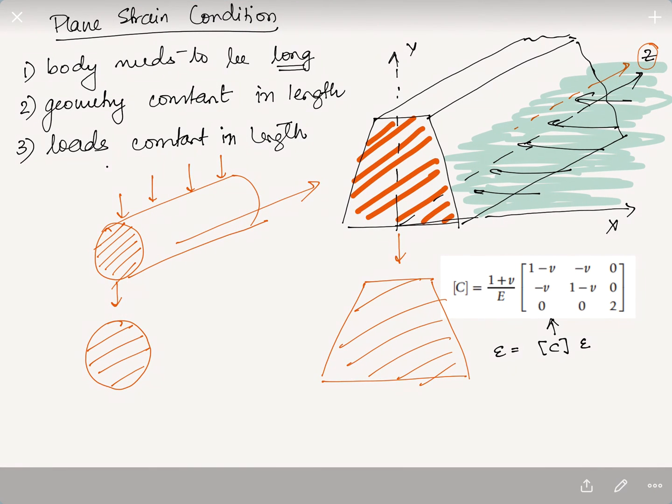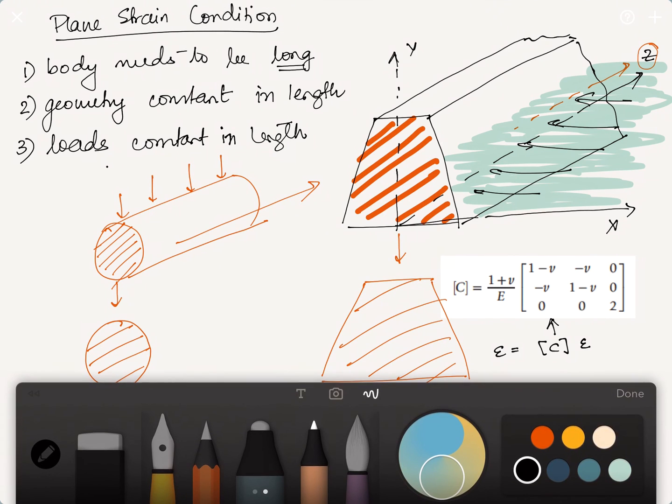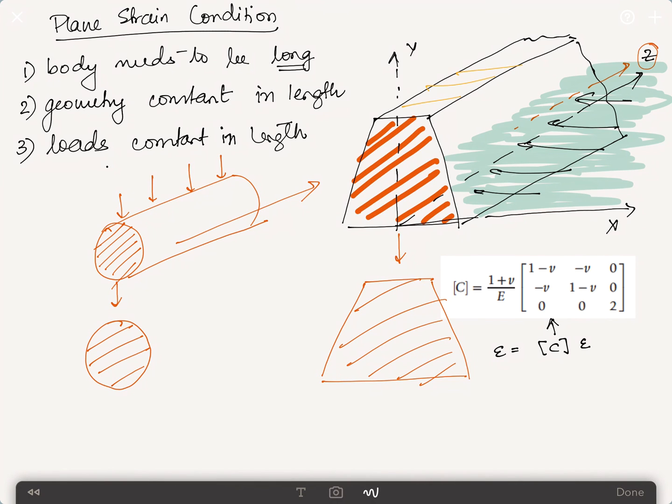The difficulty here is that you have to make sure that you've made the right assumptions and that you're able to reduce a certain part into these cross sections, which can be quite tricky. But in the end, consider the change in computational effort: instead of making this huge dam with solid elements, and the thousands of elements you would require, you just model this surface, which is quite easily meshable with 2D elements and very fast to compute. That definitely makes a very big difference. But make sure you choose the right assumptions to make sure that it is indeed a plane stress or a plane strain problem.